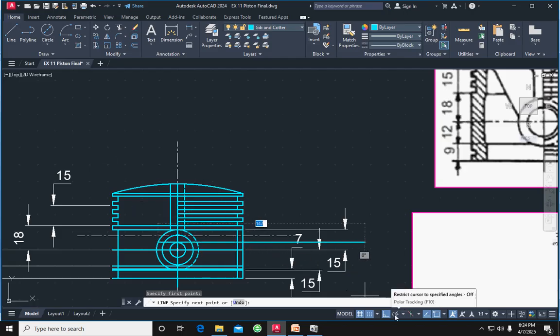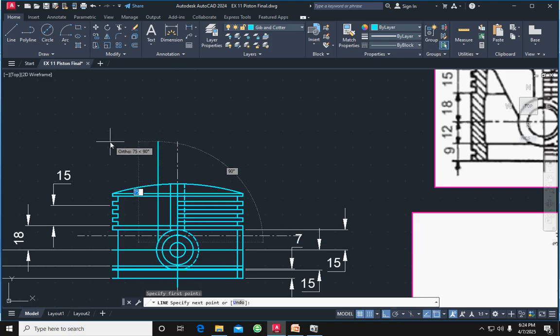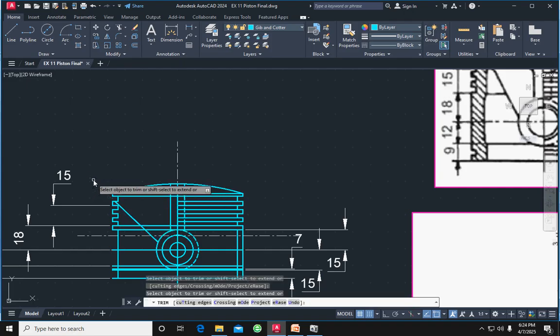In this case we have to change the value to 45 degrees. From this point we measure with the auto command, we have to offset 45, meaning a 135 degree angle. We have to draw the 135-degree angle, and I click the line. Here we want to draw a line, the 18 mm line we have to extend. Okay, we want to trim the excess line, so we have to trim. Here we want to trim. That's all.